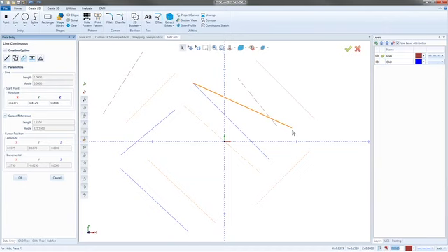So where that line is the next 1/16 of an inch measurement. And if I move my cursor up to that, you'll see there's the 1/16. As I slowly move up, it'll automatically jump up to the next 1/16 every time. Same with going left and right. So you still have the snap increment option, but now what we have is the construction geometry, which is the little button next to it.